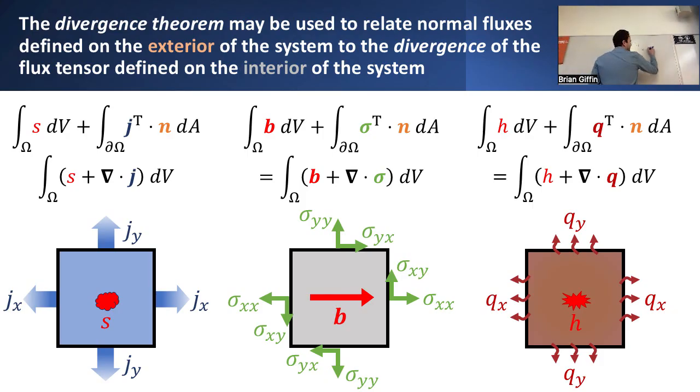So if I define my divergence of this stress tensor, which is, again, a 2x2 or a 3x3 array, really what I should get out of this is a vector, since the divergence operator, if you like, is kind of like a vector.